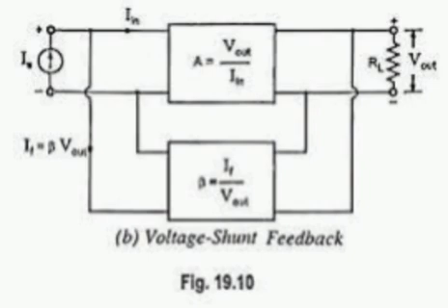For common base amplifier, AC load resistance of CB amplifier small rc equal to capital RC parallel with RL. AC load line and AC output compliance of CB amplifier is the same as that of CE amplifier.